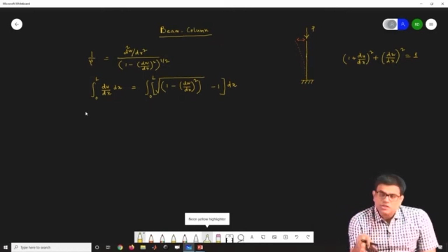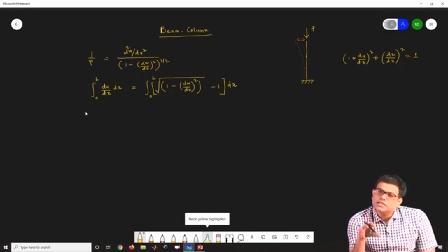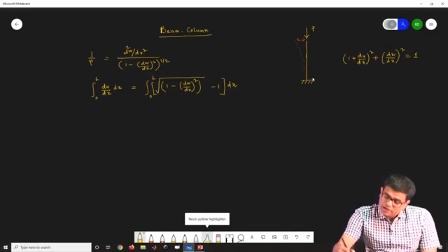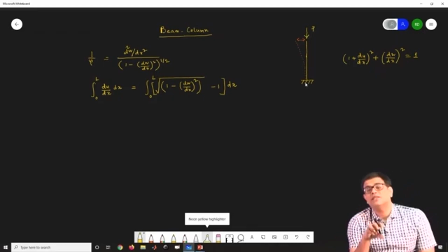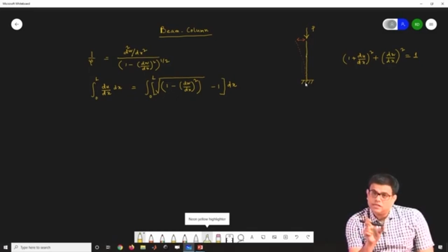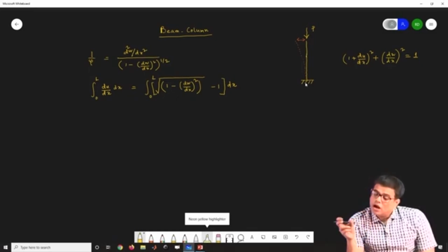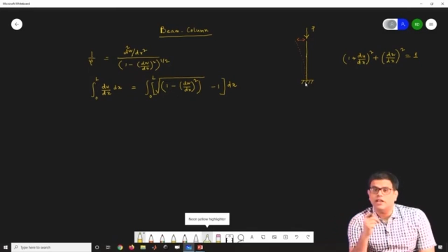Now, this axial shortening we have to consider with the axial force. So, there is again the axial displacement, which is the x displacement, or the vertical one, here it is vertical. This vertical displacement we have to represent in terms of the transverse deflection.